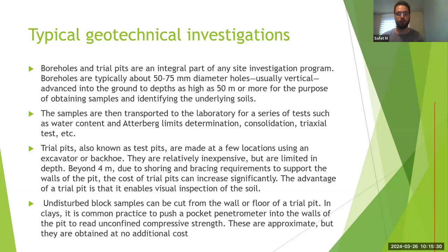So of course, after the drilling, we take samples, and the samples are transferred to the lab for a series of tests. Usually that's water content, shear strength, Atterberg limits, consolidation, triaxial, and so on, depending on the budget and on the actual design that we are looking to get.